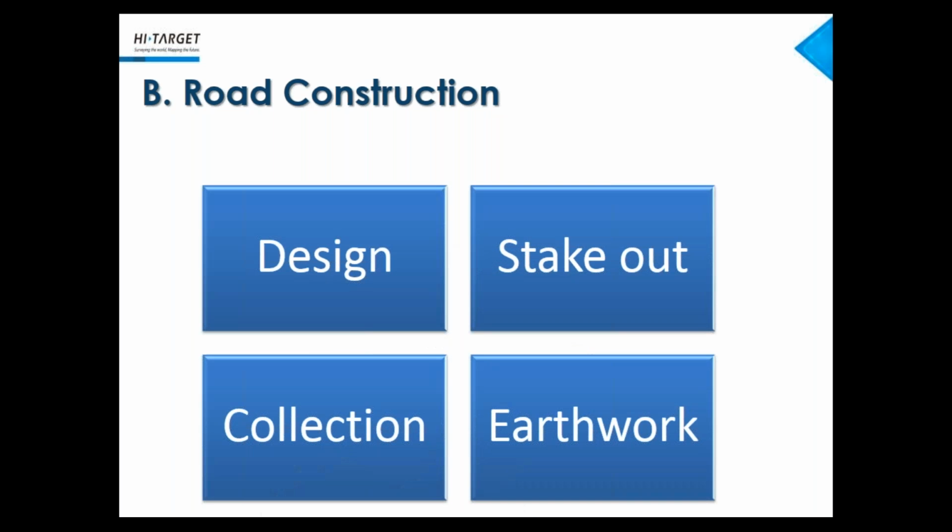For the road construction, firstly, we need to design the road files, otherwise the software cannot help you to stake out. And also in road construction projects, you need to stake out and collect the points in so many stages. You also need to calculate earthwork, either to fill or to cut.